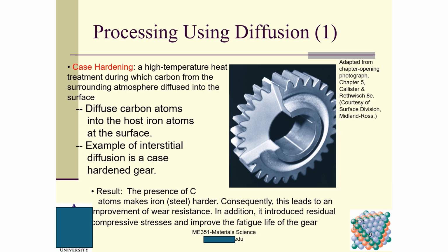Because residual compressive stresses can improve the fatigue life of the gear. Here, the specimen is a gear. Why? Because compressive residual stresses can prevent crack initiation and crack propagation.